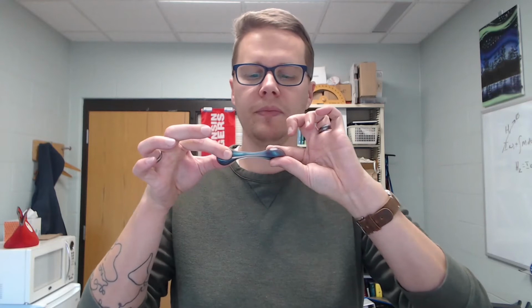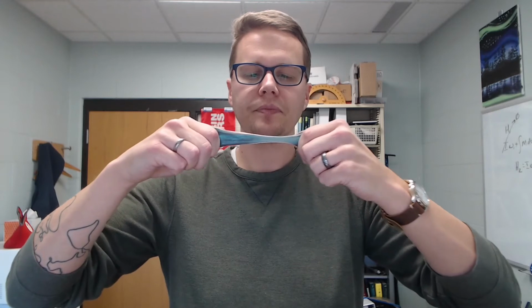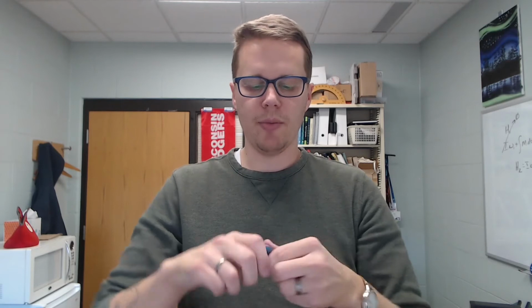But of course, what you can probably predict already is that if I take this material and I pull it slowly, it stretches and behaves in a very different way. So depending on the rate at which I apply my force to this material, I get very different responses. I can show this again. If I pull it slowly, it deforms, elongates, stretches like that. Now if I put my material back together and I pull it quickly, it fractures, and I get a very different response. It didn't stretch, it didn't elongate nearly as much; instead, it broke.